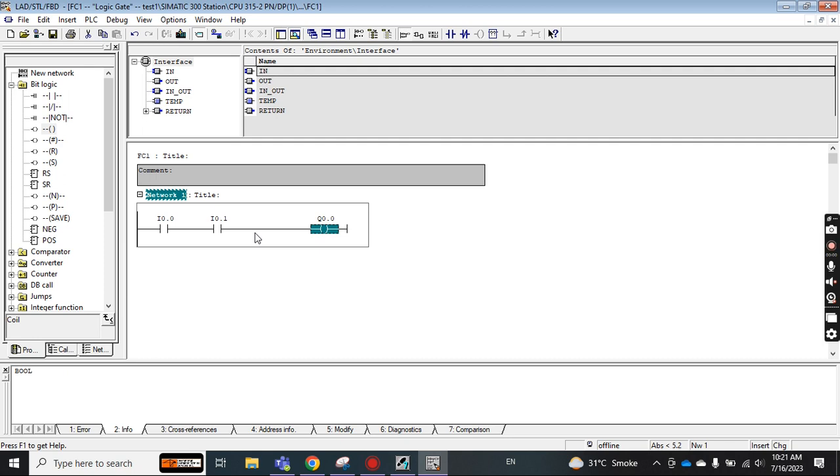In the same way, different brands use different notation. But for Siemens, all the CPUs, either S7 200, 300, 400, anyone, use I for input and Q for output. Digital input, not for analog. Analog is also IA or IW, we will learn in the later. But for digital it is I and Q.